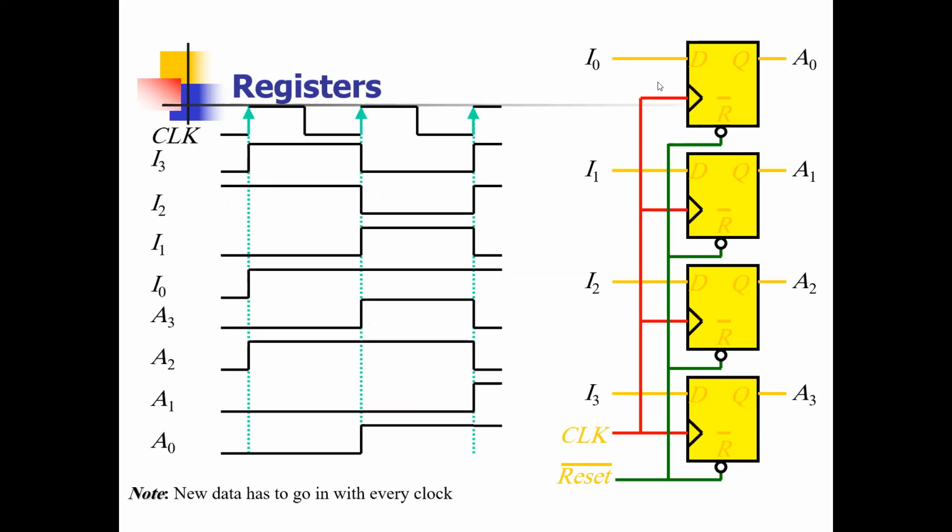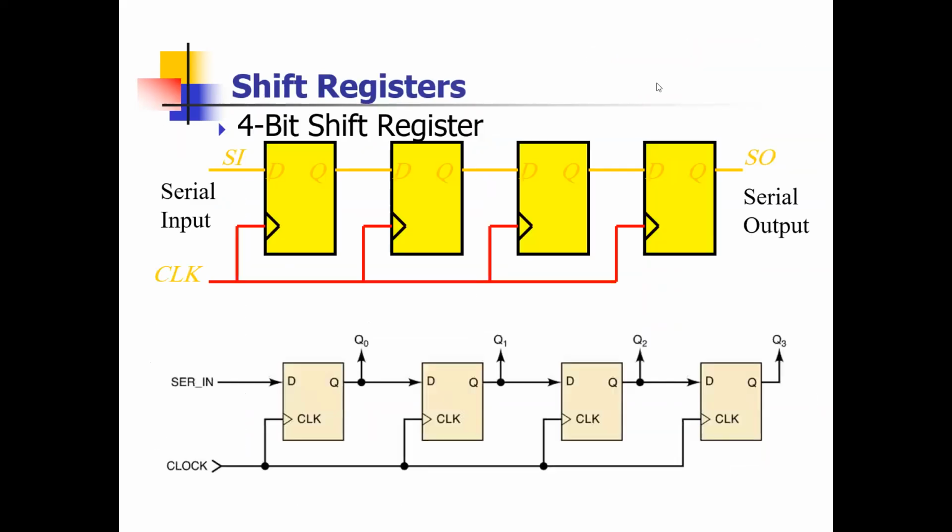Now here, shift register. Shift register means here there are 4 registers. And you know these registers we need if we want to shift the data left side or the right side. So this is the right shift register because if you look, you can see here, if there is a 1 and here is 0, here is 0, here is 0. And if I am inserting another input 1, what will happen? You can see that this one wants to come here.